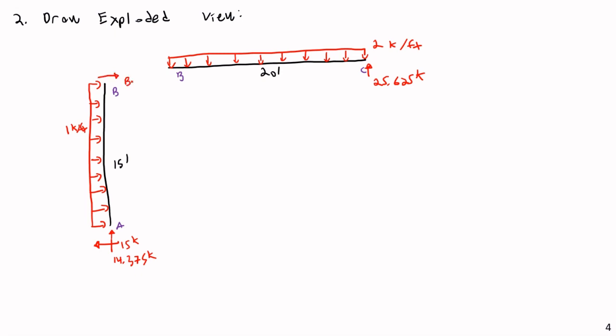Bx here, and of course just like we did earlier in the semester, when we draw an internal force, we need to draw its equal and opposite force on the other piece. So maybe I'll give myself a little room, say that's Bx, and this is Bx. Then I'm going to assume this one was up, although seeing this I know that's not really possible.